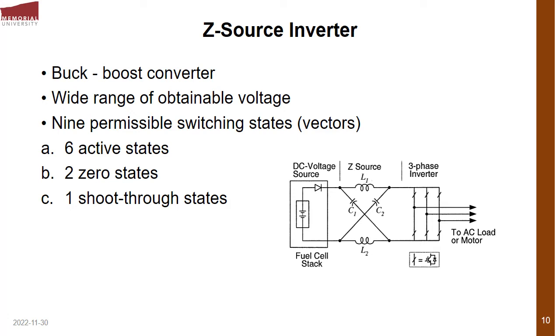We can also have the shoot through state, where in 1 phase leg both the upper and lower switches are on, or even 2 of the phase legs have all their upper and lower switches on, or even all 3.